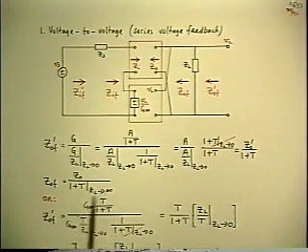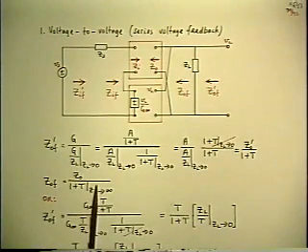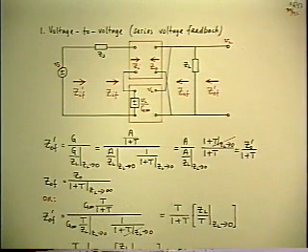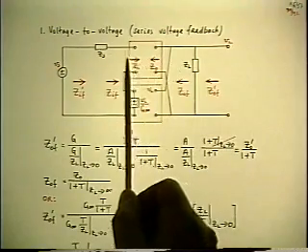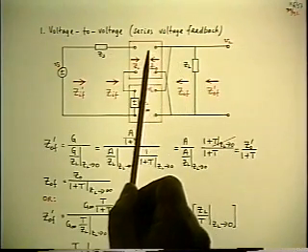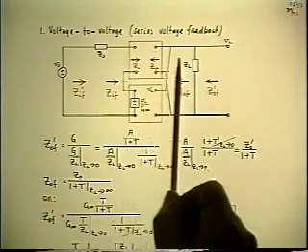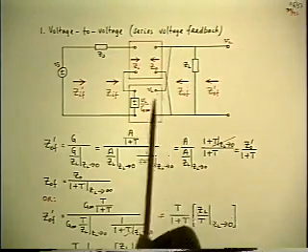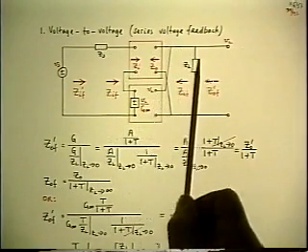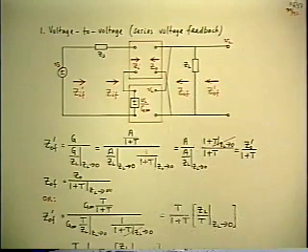And you can't say any more about it than that without knowing in detail what's inside the T. But there's one thing you know about it. T with ZL infinite is bigger than T. Why? Because the loop gain is partially determined by the impedance divider between the ZO and the ZL, because that determines how much of the output signal of the forward path is actually applied to the feedback path. So if you let ZL go to infinity, that divider ratio rises to 1. But we don't know where it started, except it was less than 1.